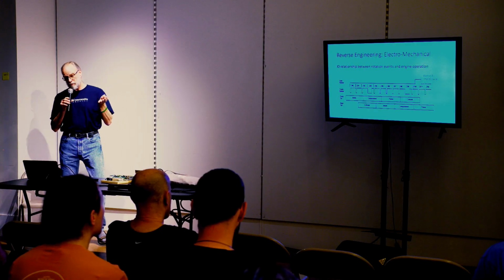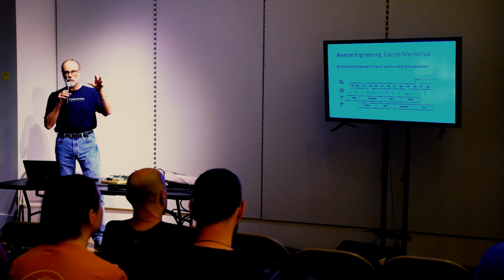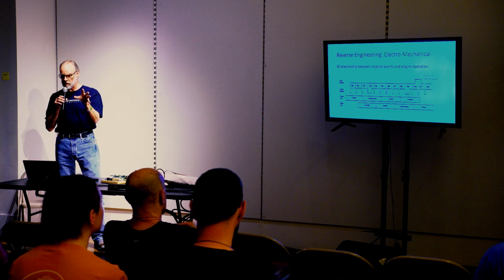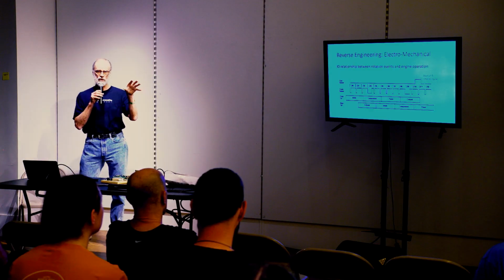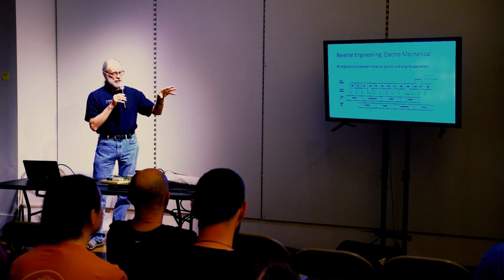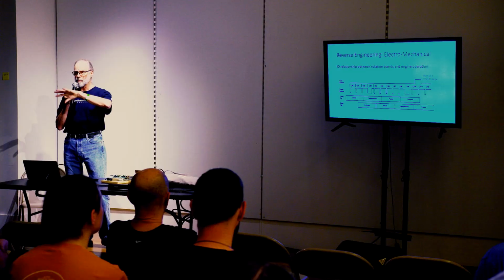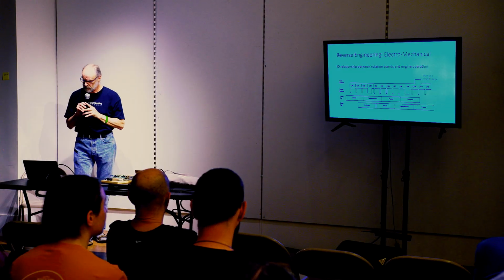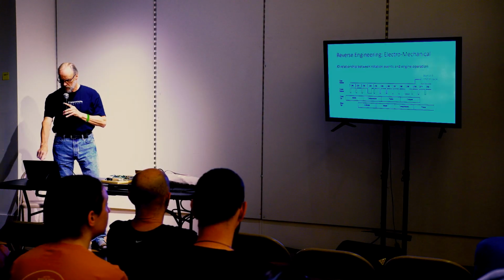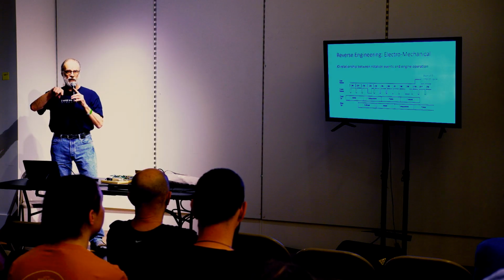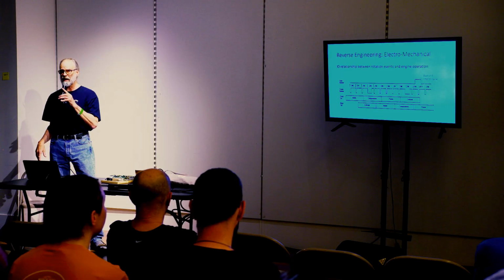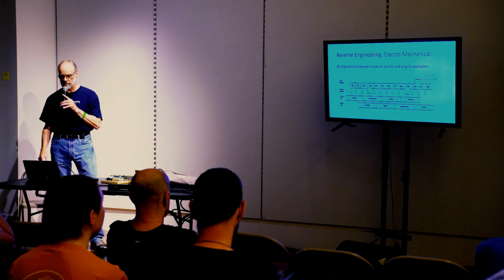Then there's the electromechanical aspects. Now that we can tell where the moving parts are, you then have to relate that to what the 4-stroke engine is doing. Which part of the rotation deals with the intake, the compression, the power, the exhaust. And you put that together. So you can see that there's 12 of these periods, 0 through 11, because there's 6 per rotation, and it takes 2 full rotations of the crank to complete the 4-stroke cycle.